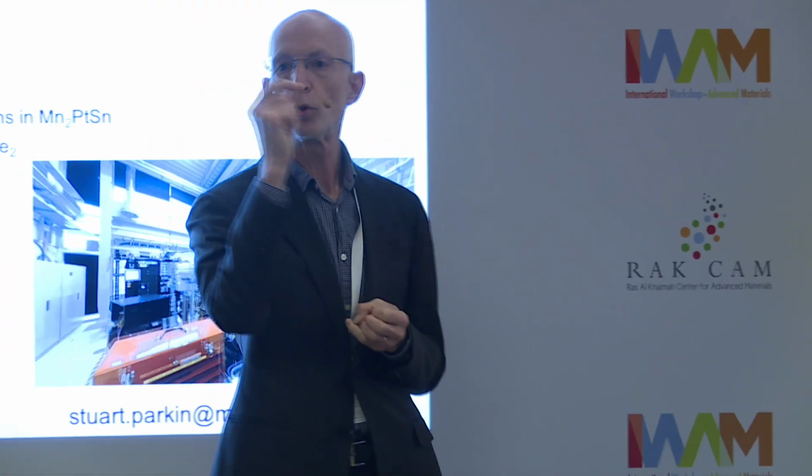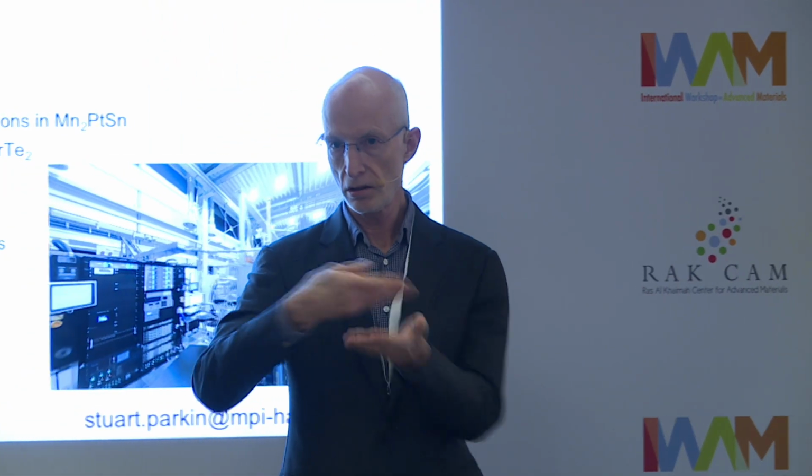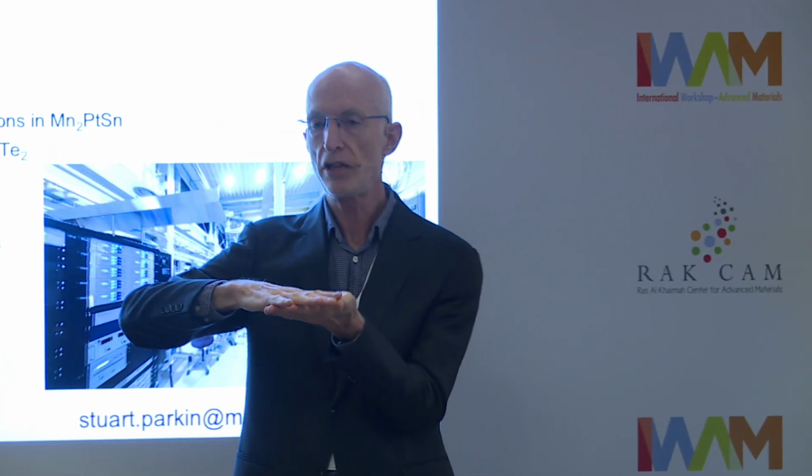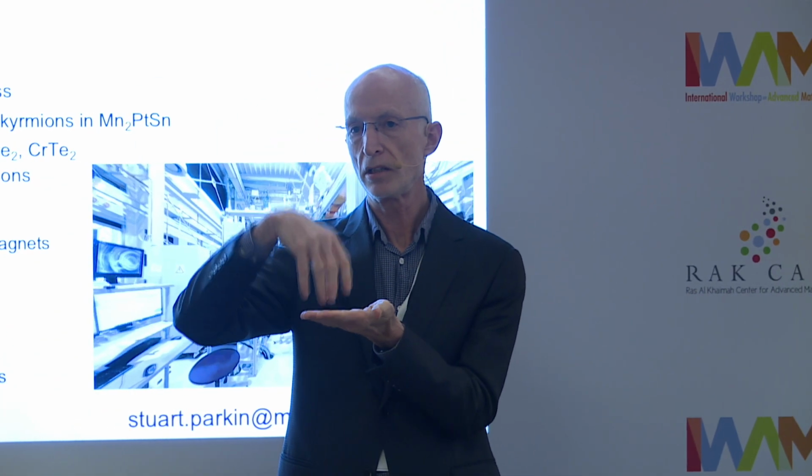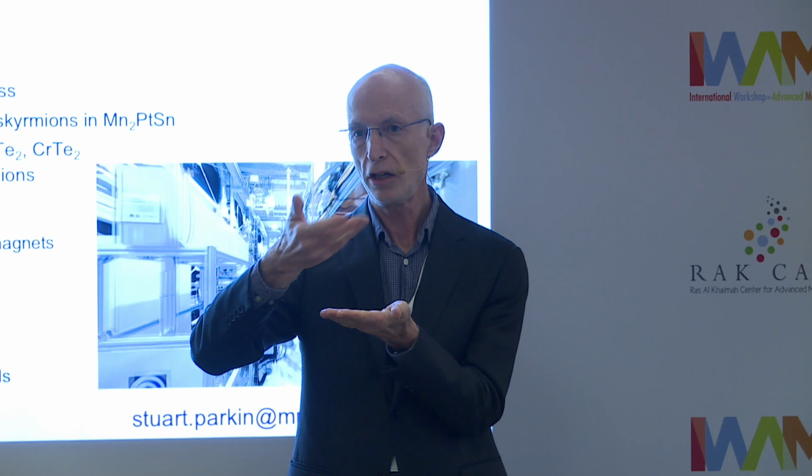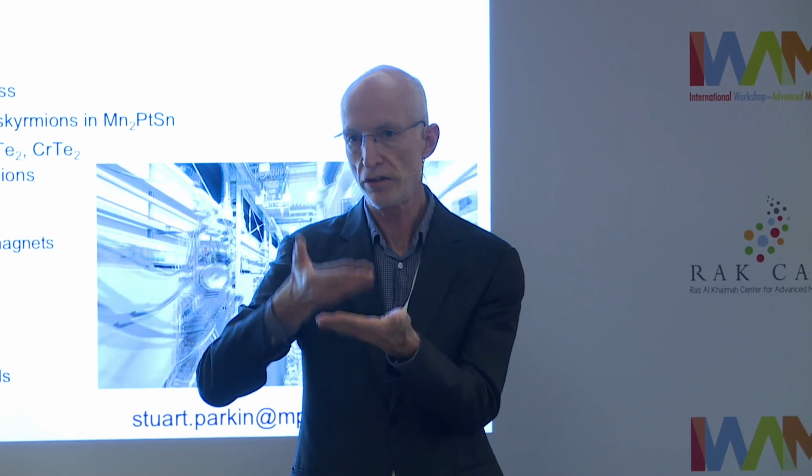Oh no, the read is, as I showed, in the one-domain wall racetrack. We integrate it into the magnetic racetrack. You put an insulating layer on top, and on top of that a counter-magnetic electrode, and you effectively build a tunnel junction into the racetrack.